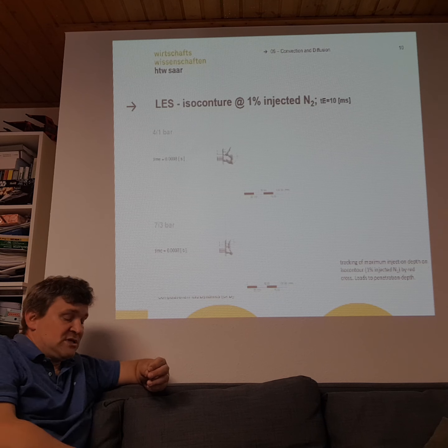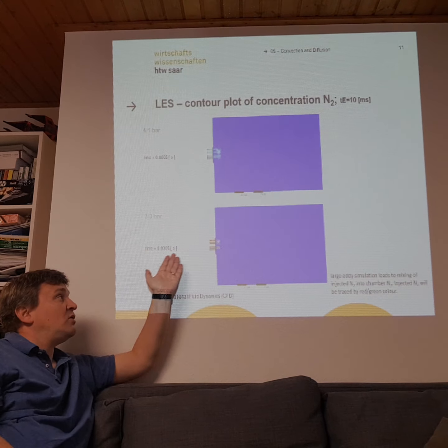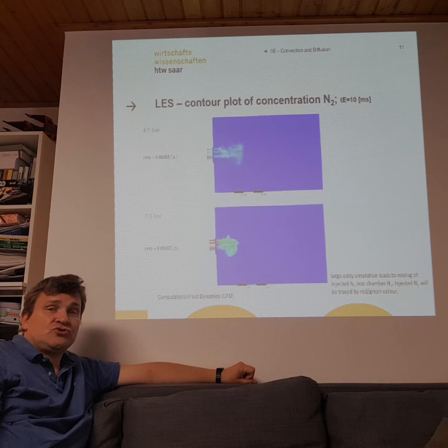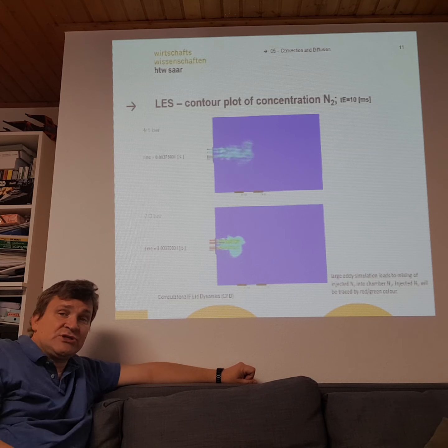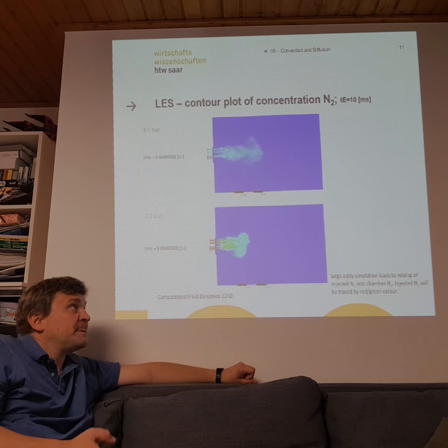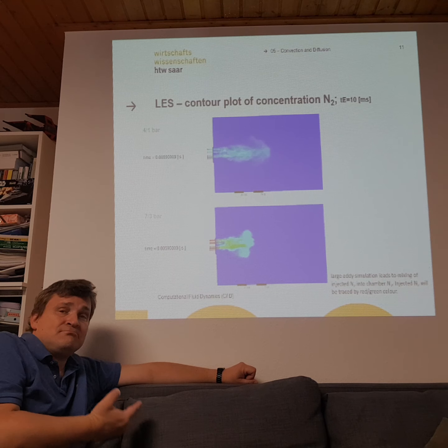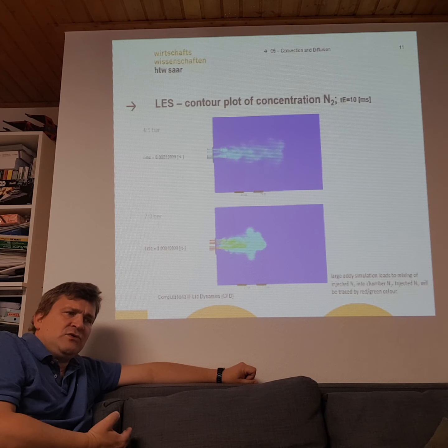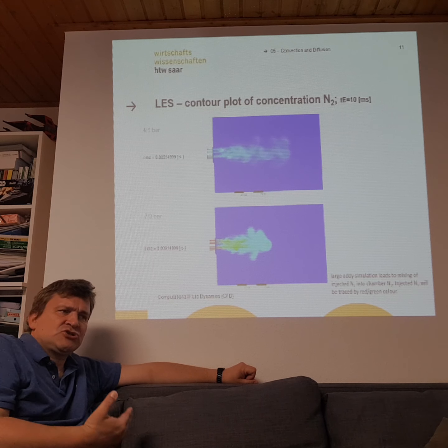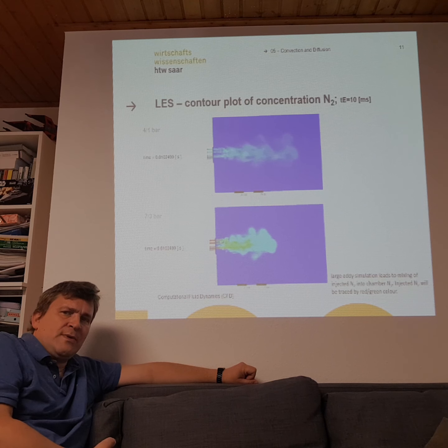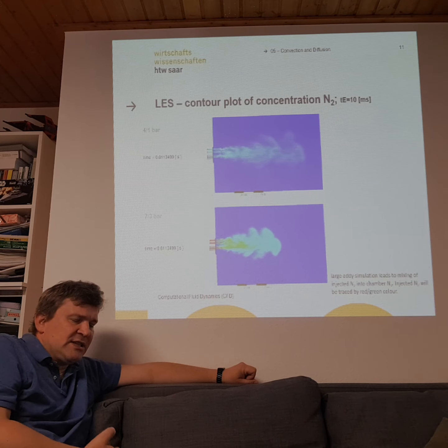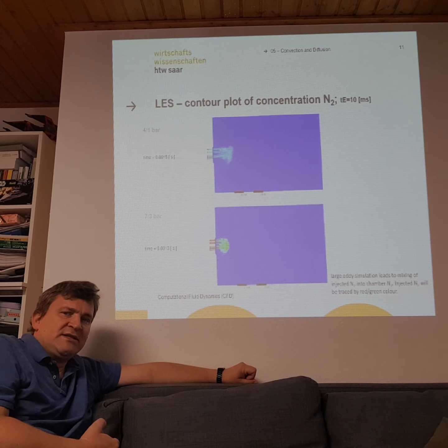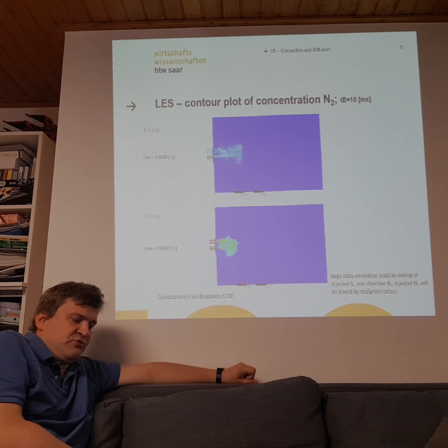If we use this kind of large eddy simulation for the turbulence prediction and the swirl prediction, the quality of the prediction is much better. So maybe if you design your airplane, if you estimate the production of swirls over the wings, a large eddy prediction is much more reliable and much better than SST prediction.